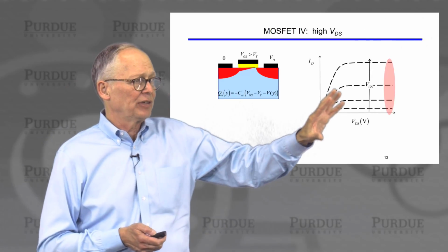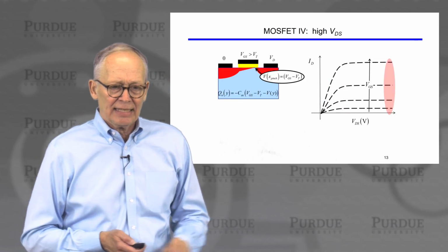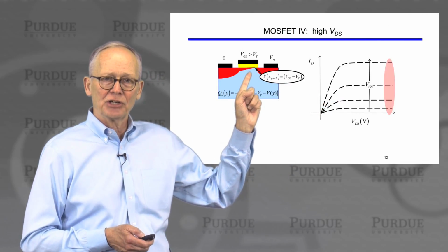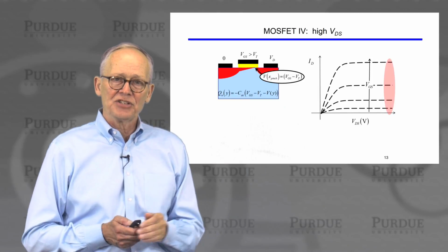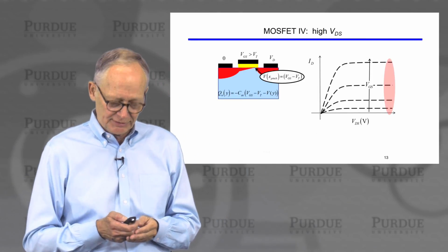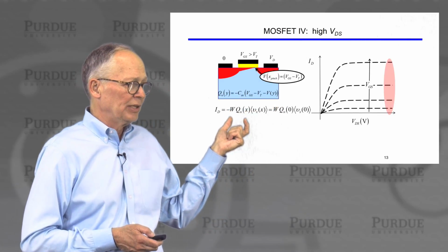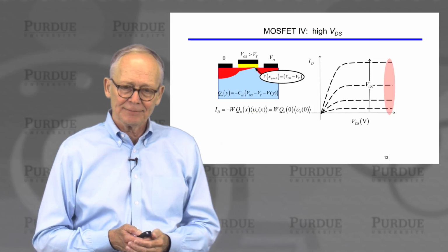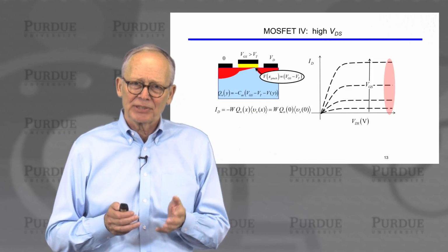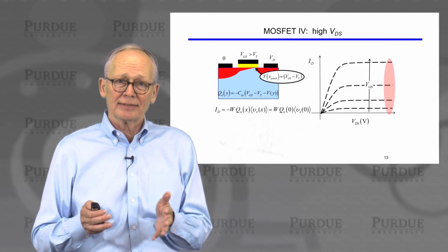Okay, so we're trying to understand the IV characteristics of this square law device. We know that at the end of the part of the channel that has charge in it, the voltage is Vg minus Vt. We've just deduced that's what puts the charge at approximately 0. So current is still width times charge times velocity. Since the charge varies everywhere and the potential varies everywhere, but the current is constant, the current is the same everywhere.